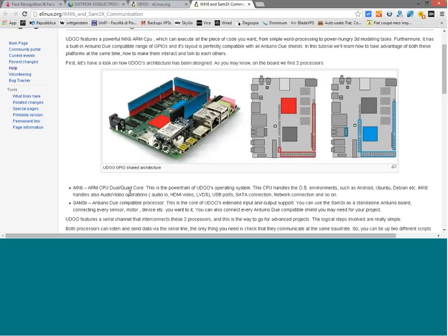On Android, instead, we use the Google Accessory Development Kit, the ADK, which is meant to connect Arduino to Android phones. So we implemented it, and this serial device is seen as an accessory. So you can use your Arduino as if it was a normal accessory on Android.